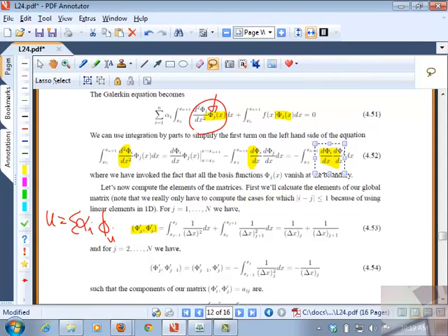But these can be done once and for all. Why? Because my basis function is independent of the problem that I'm solving. Okay? I've expressed the solution in terms of the solutions at the nodal points. So these are just known functions. This is what makes possible building general purpose solvers, because a lot of the tedious work of assembling the matrix, I have to do only once. I have to figure out algorithmically how to arrange these calculations and assemble the matrix. Okay? And then I have to solve the linear system for alpha i. Alpha i is the same as u i at the nodal points. Okay? So taking the derivative of the function, plugging it in and carrying out the integral can all be done once and for all.